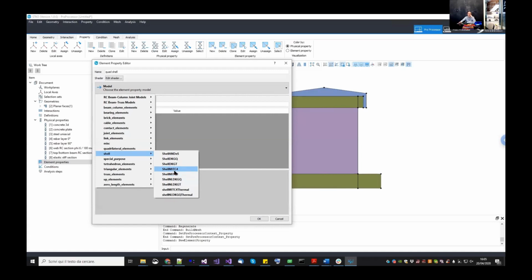This one can have either a linear or a nonlinear kinematics. And this one has, for the out-of-plane behavior, the thick plate theory, so Reissner-Mindlin theory, and it accounts for out-of-plane shear. Instead, the DKGQ and DKGT assume the Kirchhoff behavior, so thin out-of-plane behavior.